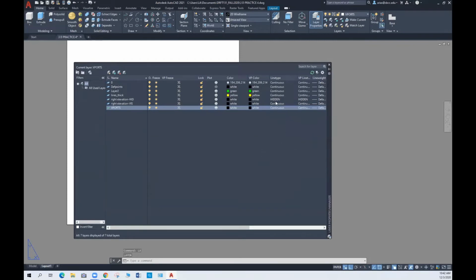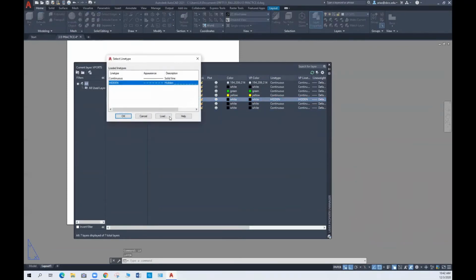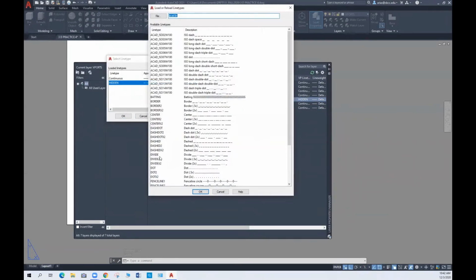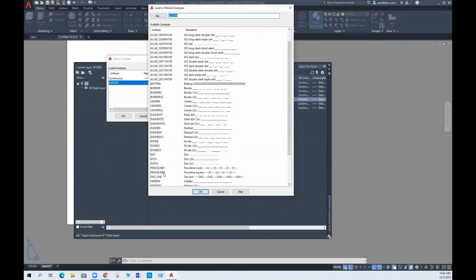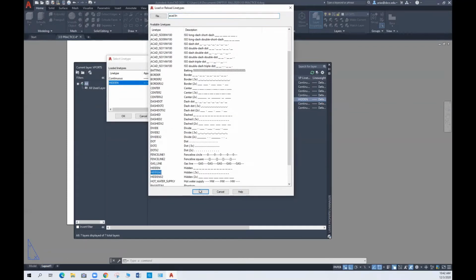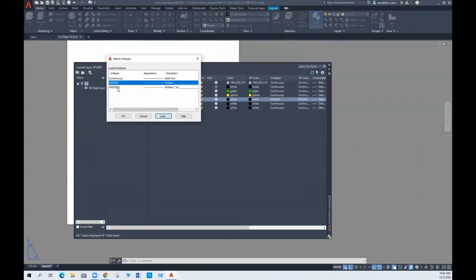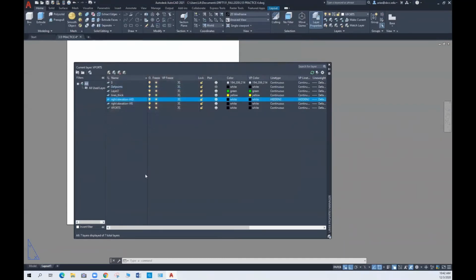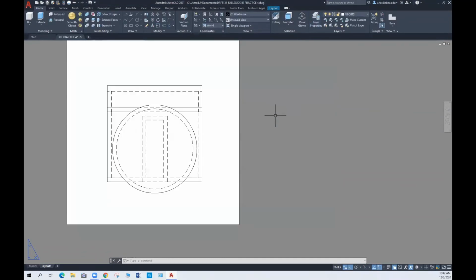If I have this to be hidden 2, it's half the size, right? Hidden 2 is half the size. And so maybe that's what I do for this particular one. See, now the hidden lines are better defined, tighter, smaller line types scale. And so that's the elevation drawing.